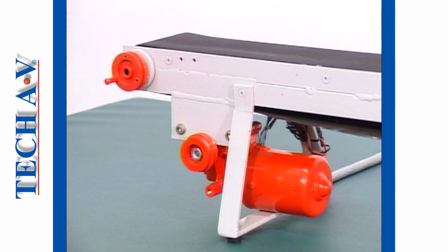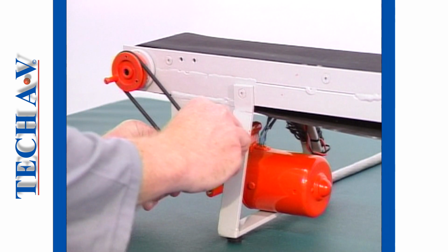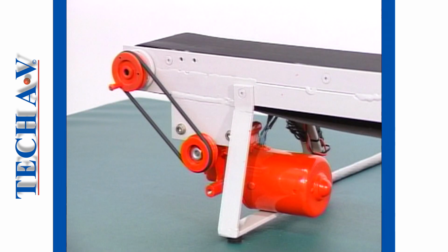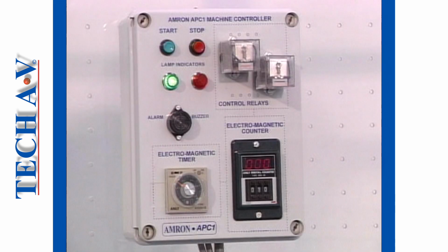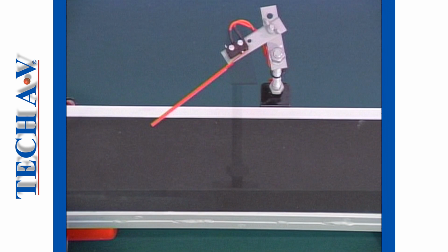So, let's begin with step 1 of our automation process, which is to motorize the conveyor. Instead of the operator having to manually operate the conveyor, we will motorize the belt and control the motor from the logic section. The next step is to replace the mechanical height gauge with a limit switch placed exactly 85 millimeters above the belt.